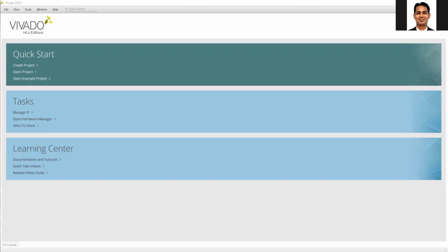So in the previous video, we discussed the DMA and how the DMA can help the processor perform memory transfer operations. So in this lab, we are going to build a MicroBlaze and DMA based embedded system where we will read the data from the block RAM, pass it to any signal processing IP, and the output of the IP is then received by the DMA and stored back to the block RAM. And this DMA is configured by the microcontroller.